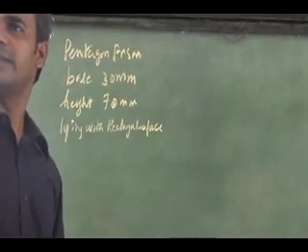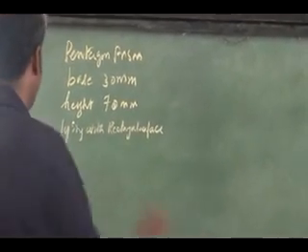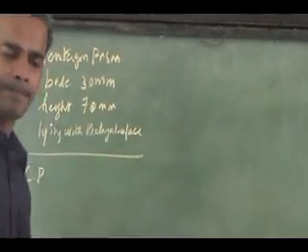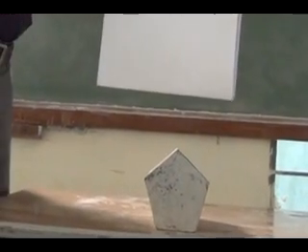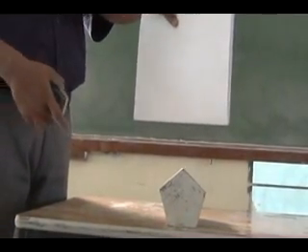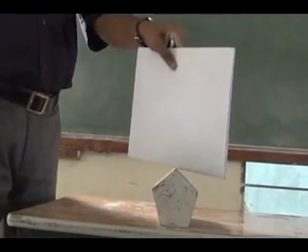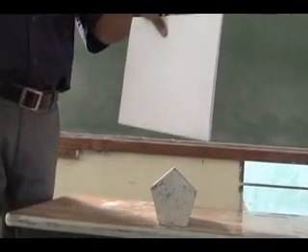It is not inclined, right? This axis is perpendicular to VP. Then the cutting plane: it is cut by a plane like this. What is this orientation? Tell me. Perpendicular to HP and inclined to VP. Same condition, inclined to VP. So that inclination I am going to tell. Then where it is exactly cutting the solid, that I am going to give. That is exactly bisecting the axis.